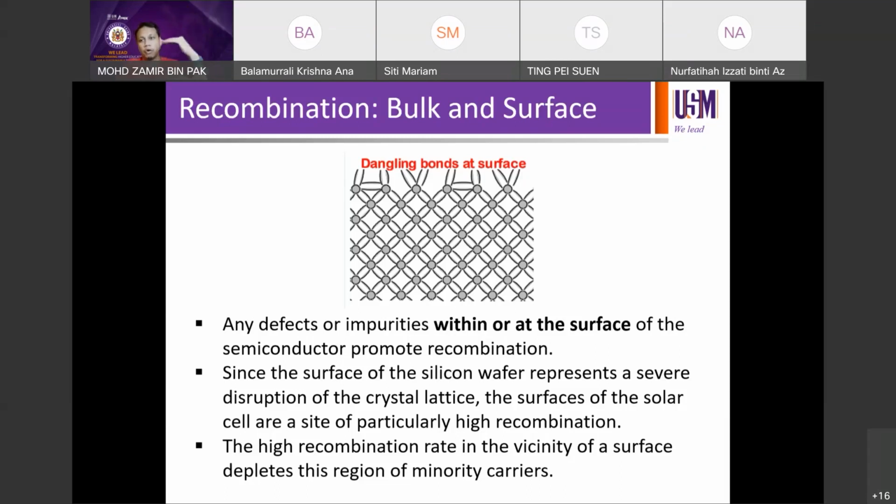On the other hand, if you grow bottom up, you build, right? You deposit on your glass, on your plastic, on your silicon, on your whatever. You are growing. When you grow, when you stop growing, you will end at a surface, isn't it? You would deposit only like 50 nanometer, 100 nanometer, 1 micron, 10 micron, whatever. So you will also end up with a surface, and that surface is also a recombination center location. So it's not only limited to the cutting process from an ingot, but it's also due to the growth process that will also result in formation of dangling bonds.